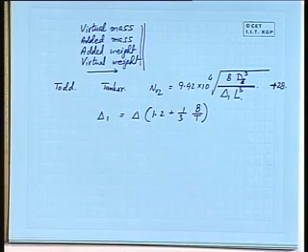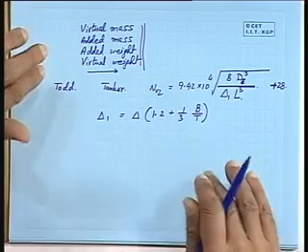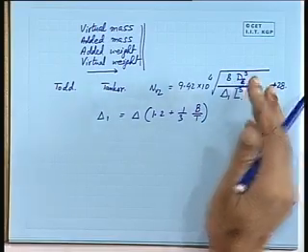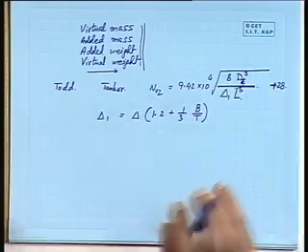How much of which tier is contributing, that comes. So what is its range? If it is 60%, 40%, 50% or whatever it is, you may have one tier which is extending for 80% of the length, and then you are tapering it down to 70%, then 60%, then 40%, then that has to be taken into account, and finally the rule actually gives you how to calculate this DE based on those tiers.